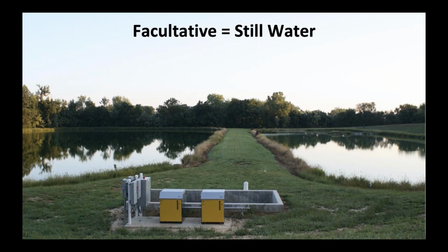The downsides are they take up a lot of land. If you don't have the land, then they're tough to deal with. And eventually you do need to remove sludge. This is the biggest issue I see, and this is why we have a whole module on biosolids within the Lagoon Masterclass, a whole set of courses on it: biosolids do need to be managed at some point. Sometimes people forget because they don't have to do anything with the lagoon, and they start to think that they don't have to do anything with the lagoon, when in fact you do have to remove biosolids at some point.